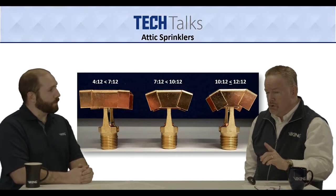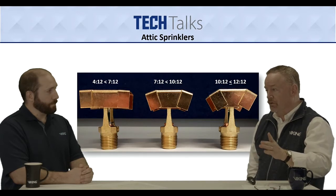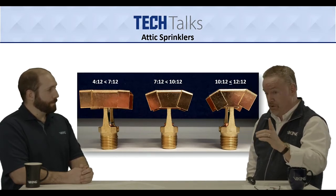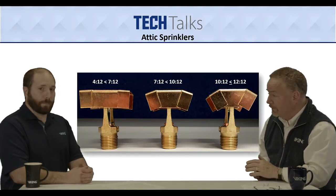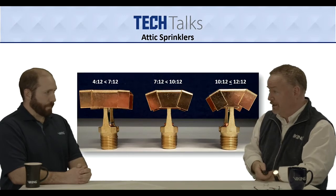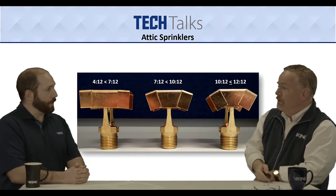So these are upright sprinklers, and typically in a sloped ceiling, the sprinkler deflector is intended to be designed parallel to the roof slope. That's correct. But that's not the case with these. Correct. So these are always vertical installations. Yep, they're going to be vertical in the upright position, and the deflector is going to do the work for you for its slope design. So that's why it's important to know what the slope is and get the order right, get the sprinkler K factor, because each one of these has a different SIN number. Absolutely correct. Each different spray angle and each different K factor has a unique SIN.